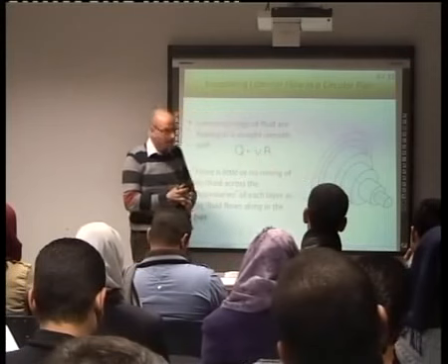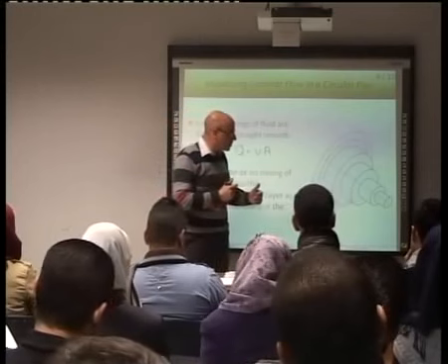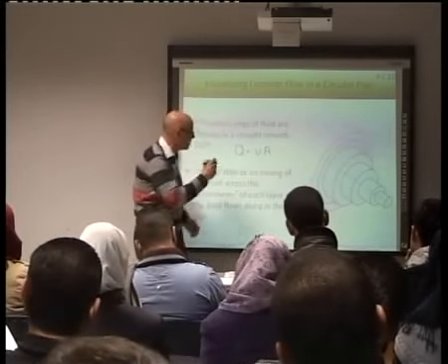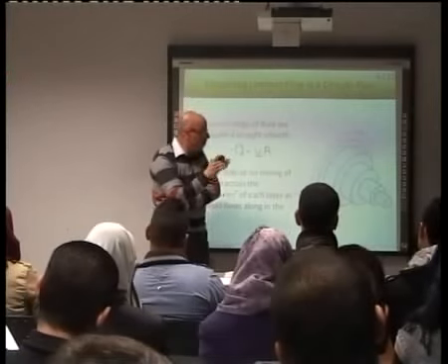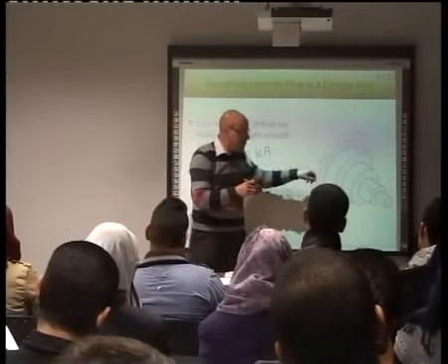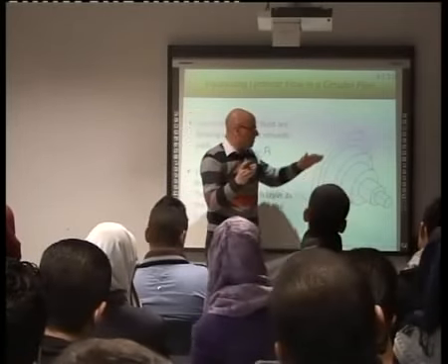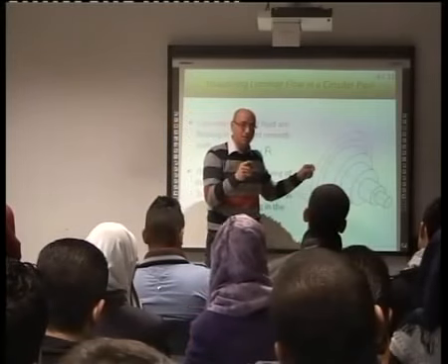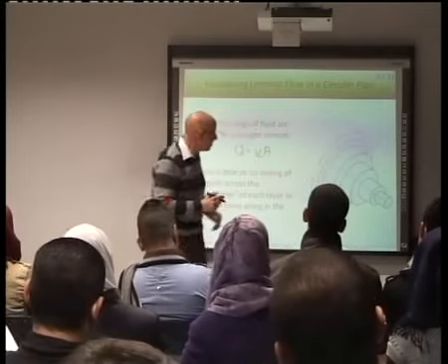This is very important. I think this is the major idea from putting this figure here. Two things: that the laminar flow is like a sheet flow, layer flow, and the second thing, which is more important, that we have a velocity distribution. Yes, we can describe the velocity as an average velocity, an overall value for the entire pipe. And by the way, in hydraulics we deal majorly with average velocity, but in this chapter they distinguish the velocity at the center line being the maximum velocity, and the velocity at the boundary itself being the minimum and equals 0. And thus we have a velocity distribution that we will come across later on.